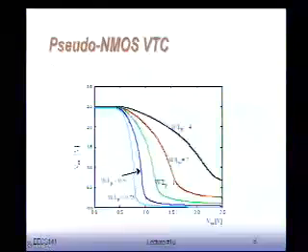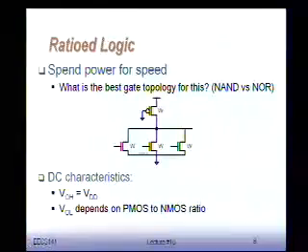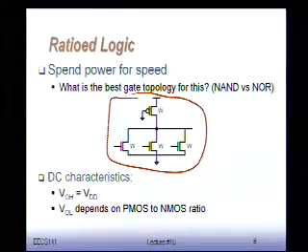So here's an example of such a gate. You choose your NMOS devices, and you make your NMOS device, let's say, W size. And you have to choose the size of the PMOS device in such a way that my resistive divider gives a VOL within the range I wanted. Actually, it turns out that making them all the same size works quite nicely.